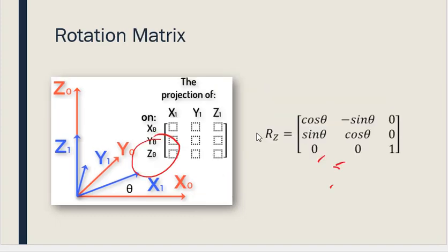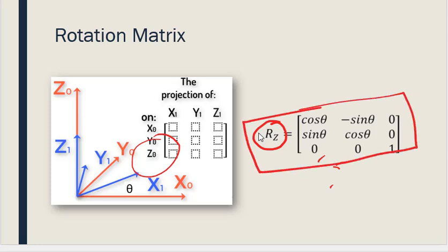And in the matrix, another important one is the rotational matrix. Rz means rotating about the z-axis. You have to remember that when rotating about the z-axis, the shape will be 1 remaining, 0 0, and cosine, minus sine, and sine theta will be here.